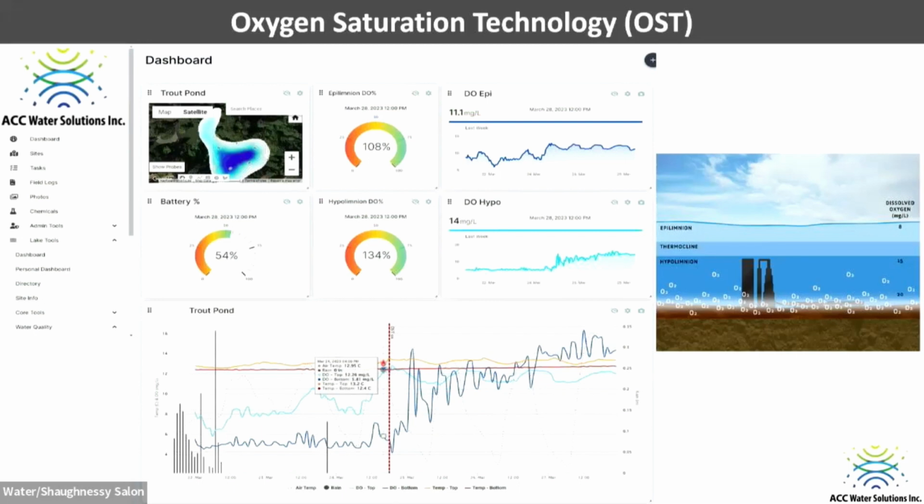So within a few days, you can see in this particular little pond, this is the day it was turned on. And I can't quite read the dates here, but it was, I think, about 2 days, Dhaval? Yeah, about 2 days. The temperature wise, it was pretty well mixed, but there was so much sediment and oxygen demand that the oxygen movement from the surface couldn't keep the sediments oxygenated. So within 2 days of adding this, we see the oxygen levels returned to the levels that we want. And then the system turns itself on and off. So it's a very, very effective, practical way to do things. It's not the right fit for everything, but it's a pretty good solution.